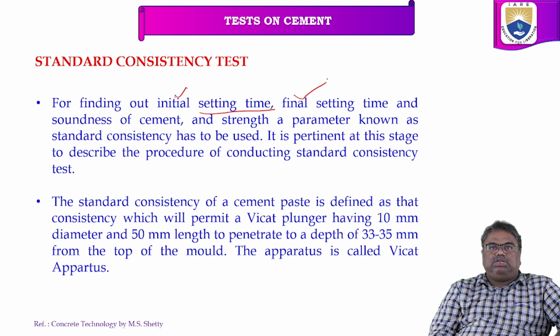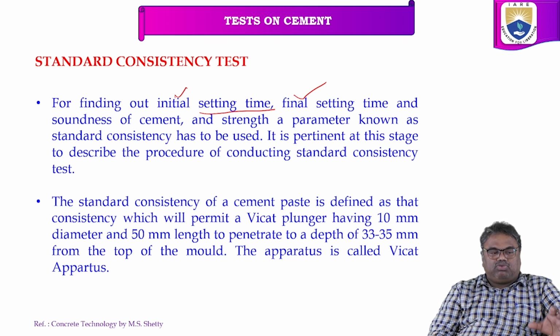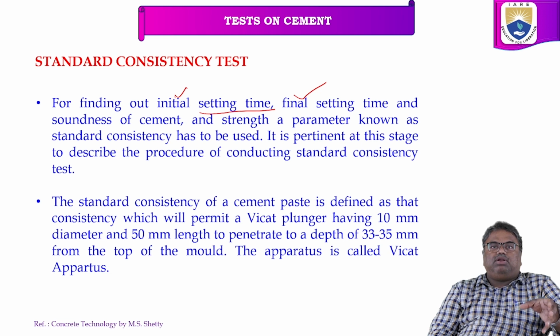To know the setting time, we have to make the cement paste of standard consistency. Consistency cement paste is required to know the initial setting time as well as the final setting time. For that, we have to conduct this standard consistency test. So this is very, very important.